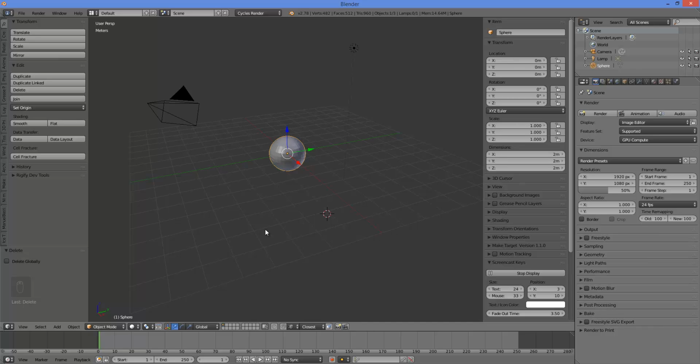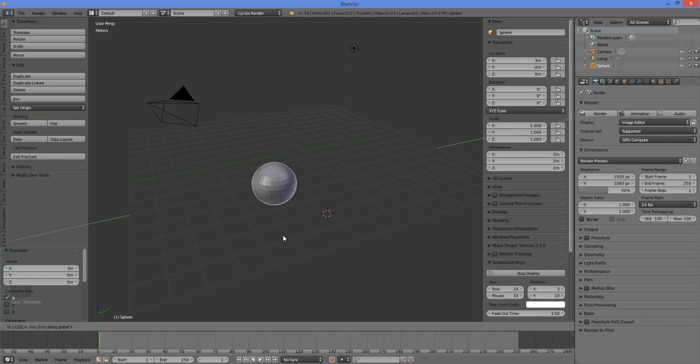Now, let's move an object of a known distance. Select the sphere, then type G, then X, then 3. The sphere will move in the X direction of 3 units. Now try to move it in the negative Y direction. Type G, Y, -2. The same is true for rotation. Type R, Z, 45. The sphere will rotate 45 degrees around the Z-axis. You can also scale the sphere. Try, for example, to flatten it, typing S, Z, 0.5 or simply 0.5.